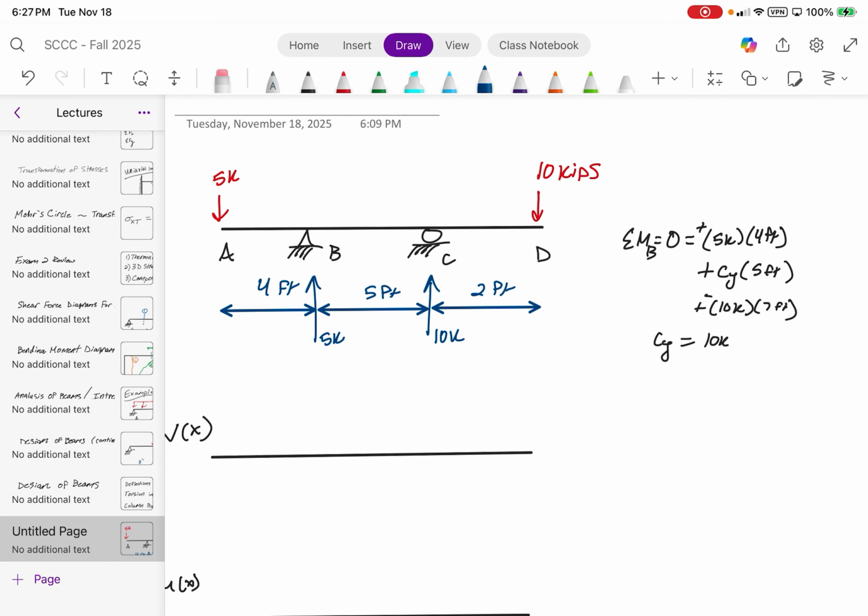Next, follow tip to tail. All right, 5 kips on the very left-hand side. We start at the very left-hand side of the beam. You have to go down 5 kips. Is there anything between A and B to cause an increase or decrease linearly? No. So it's just a straight line across and then jumps up. And this is negative shear with a value of 5 kips.